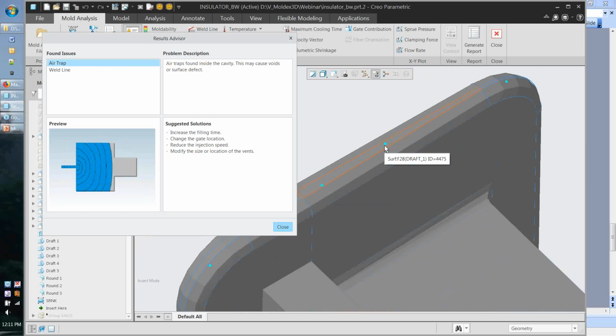Some materials are more prone to having problems with air trap than others. And tooling also plays a part, such as venting of the tooling. You could simulate the part and everything could be wonderful, and if they didn't do a good job of venting the mold when they built it, you could end up with air trap problems in the real world that might not have existed in the simulation, for no fault of the simulation engineer or the process they used to get the analysis.